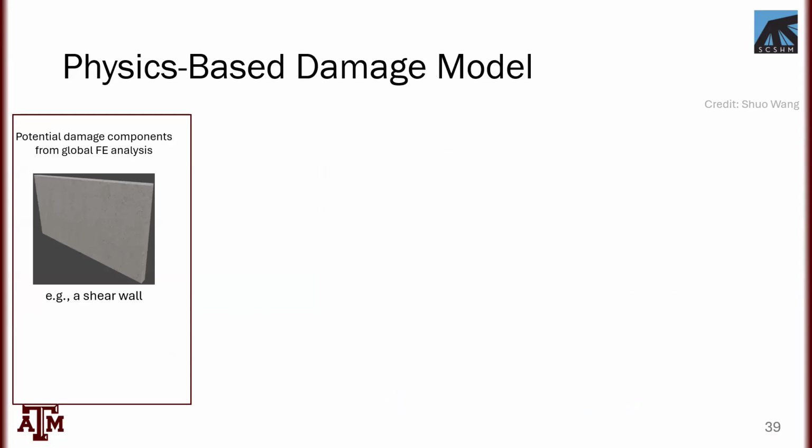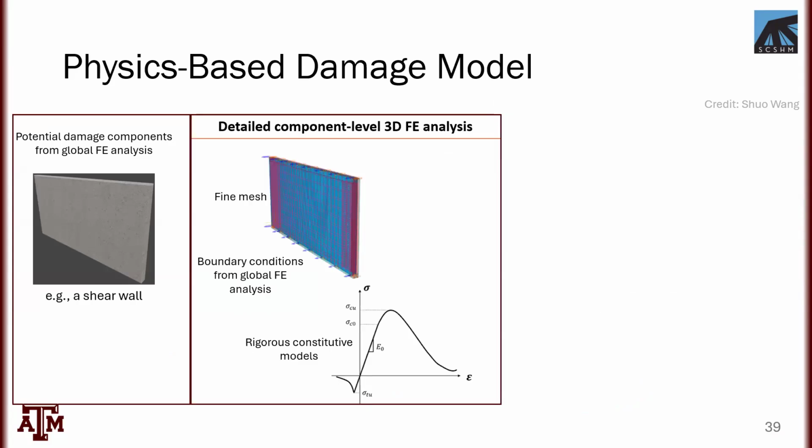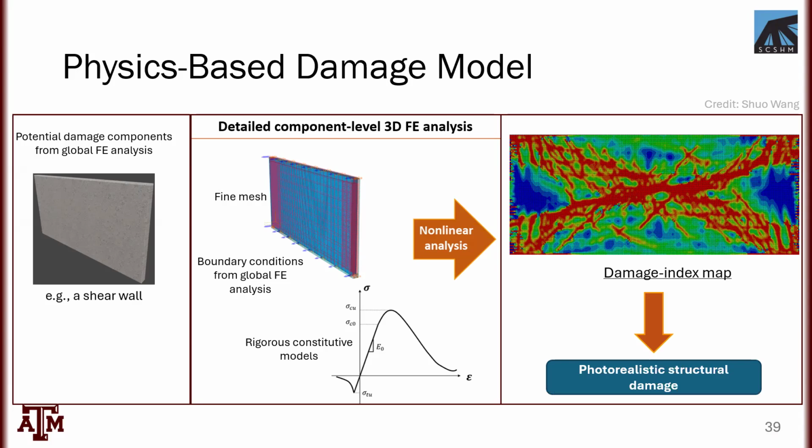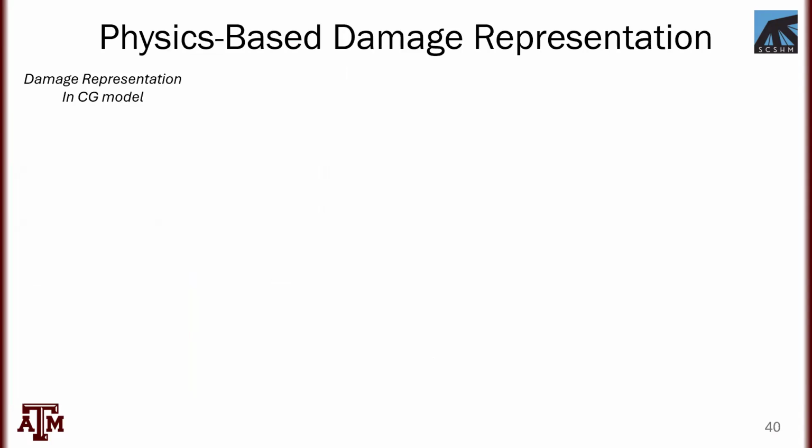So we zoom in to the component of interest, perform our detailed component-level 3D analysis, and we get highly nonlinear analyses like this, like a damage plasticity model showing you where the cracks are. And we can convert this into a photorealistic structural simulation. And I'll show you what this looks like.